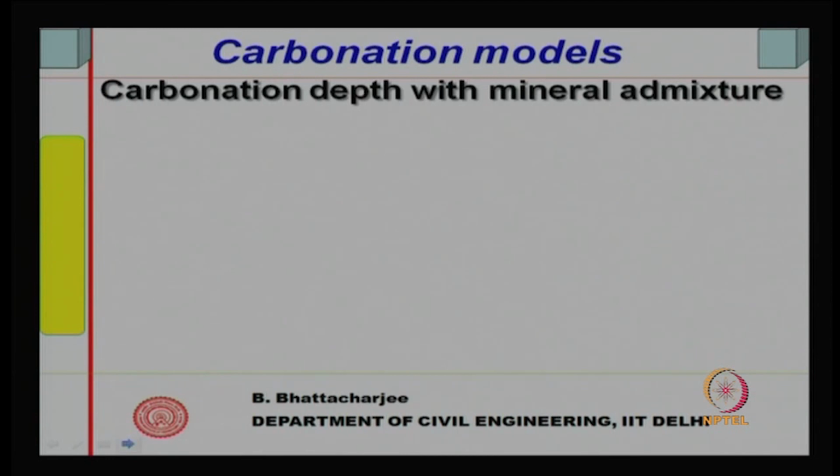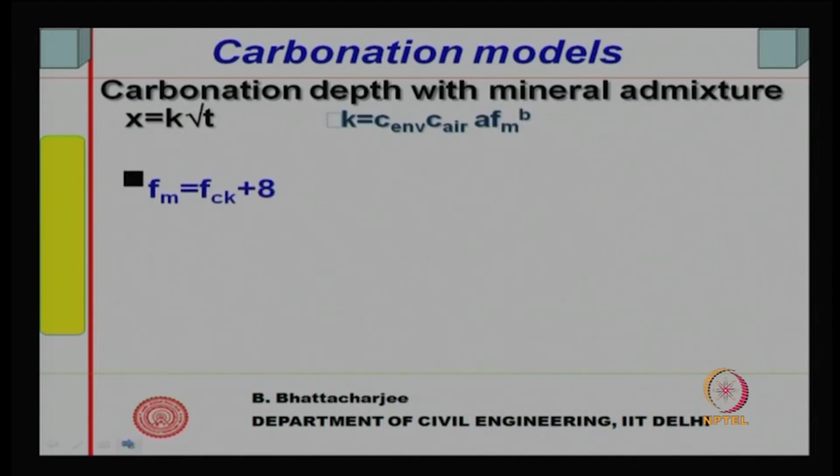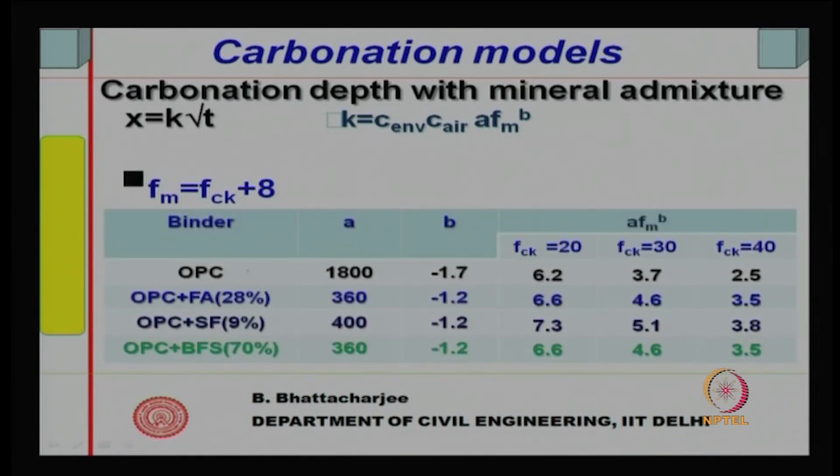Well, one more durability aspect related to the corrosion process is carbonation depth with mineral admixture. This will surely reduce with mineral admixtures, because this depends upon alkalinity, calcium hydroxide. So, if calcium hydroxide is consumed by the atmospheric carbon dioxide, the pH of concrete reduces, and that is carbonation. So, it has been observed that if you use OPC